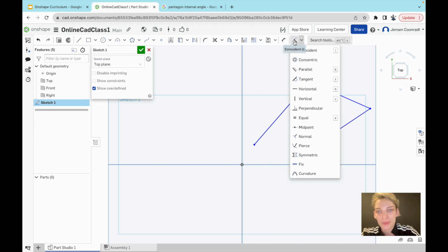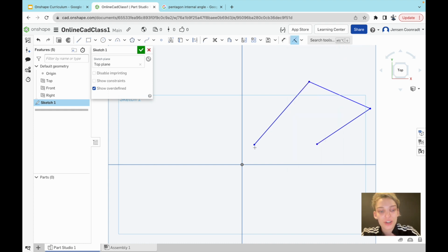And firstly, to close up the triangle, I'm gonna use the coincident thing. There's no reason why you couldn't have just at least closed the triangle. It automatically should snap close. But if you're like me and apparently can't draw a triangle, you can use the coincident constraint down here, hit this point, and look, we got a triangle.